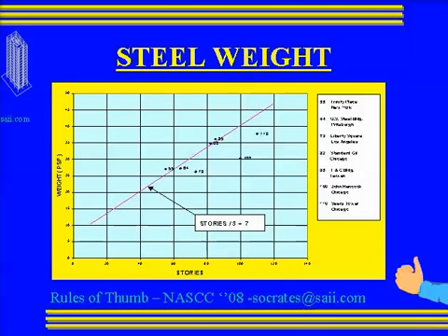This actually came from Fazlur also, although no credit is given to him here. But I did not hear it from him. The first time I heard it was from Bill Baker. But when I did some research, I found out that it came from Fazlur. If you wanted to find out how many pounds per square foot you have in a high-rise project, you take the number of stories divided by 3 and add 7.